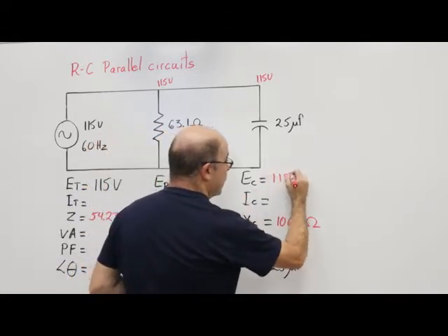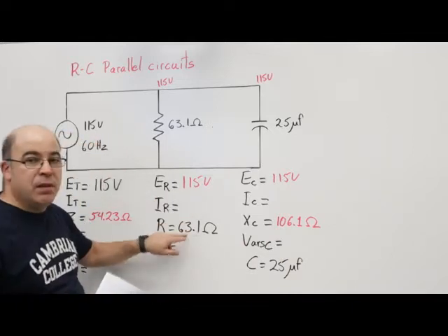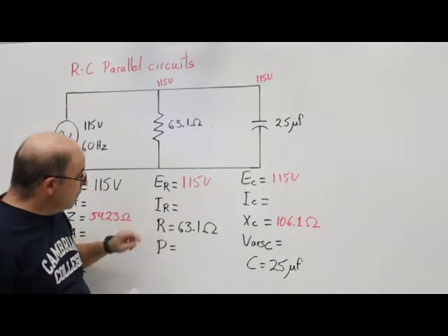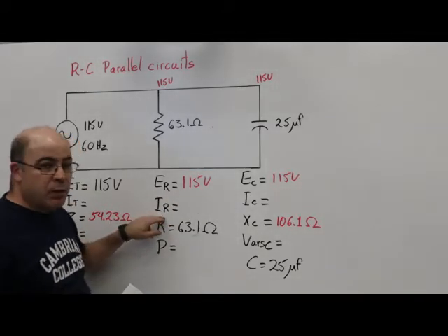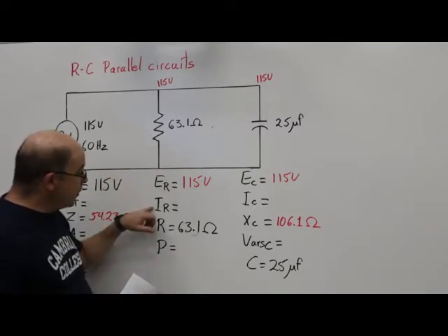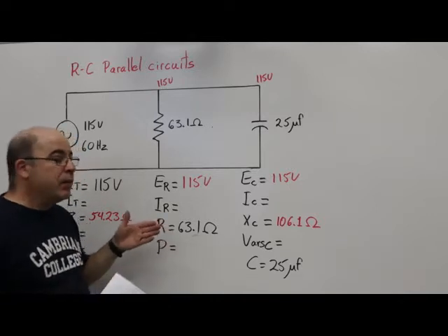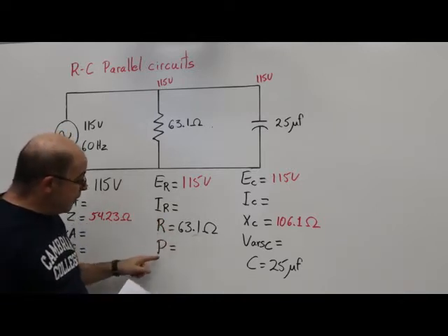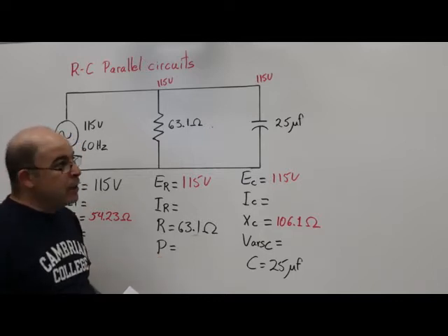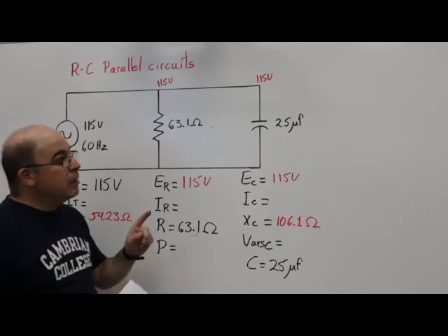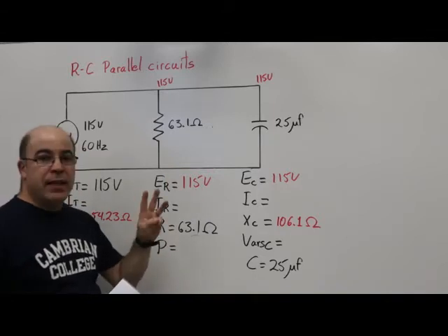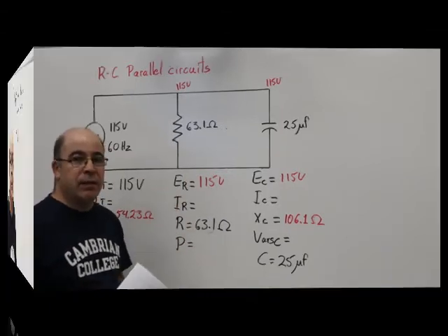Same thing applies here. Well, now that I've got two values, it's simply using Ohm's law, where I could calculate for the missing value of current in this branch. And that's what I'm going to do next. Once I have this, though, I'll have a value in my calculator that lets me skip to the next missing value and calculate the power in watts. So that's where I'm going next. I'm going to erase the board, set up, and we're going to do steps 3 and 4 consecutively.